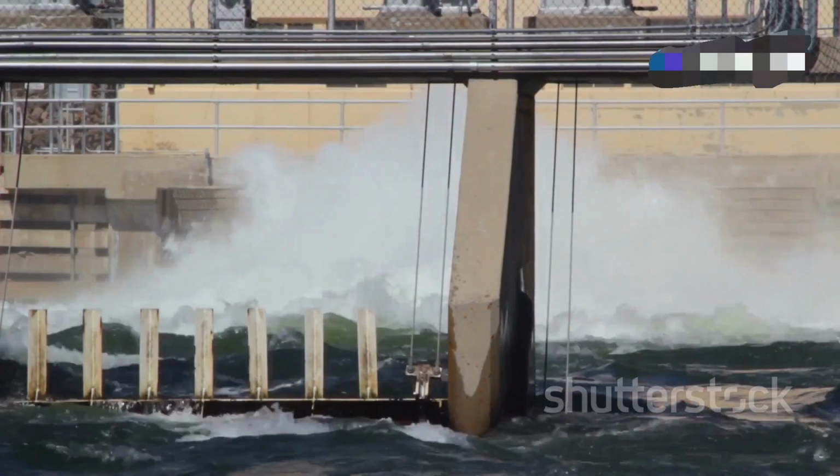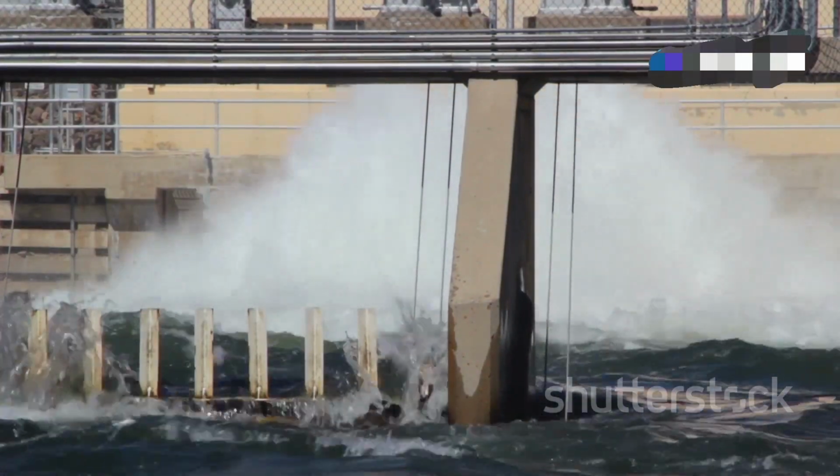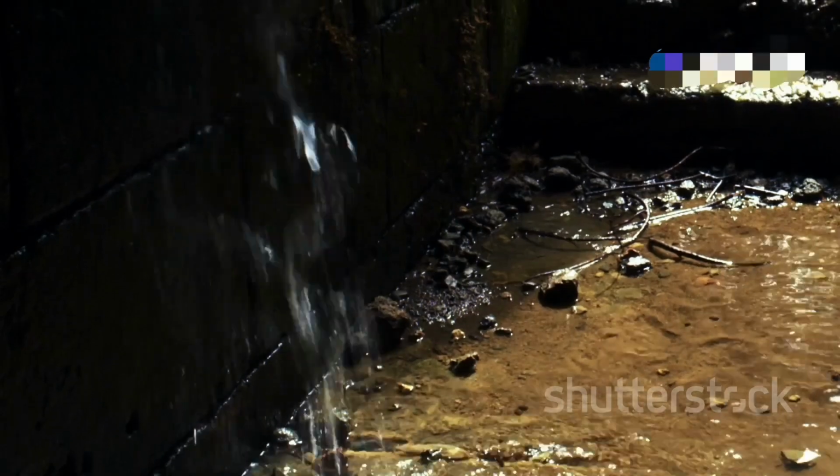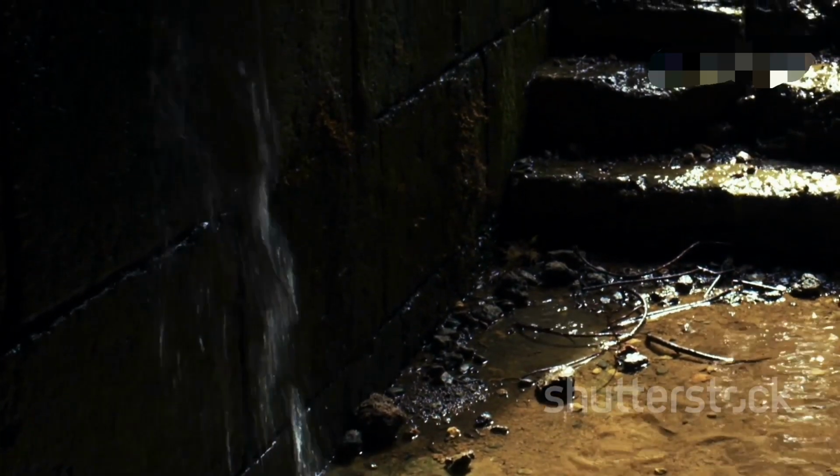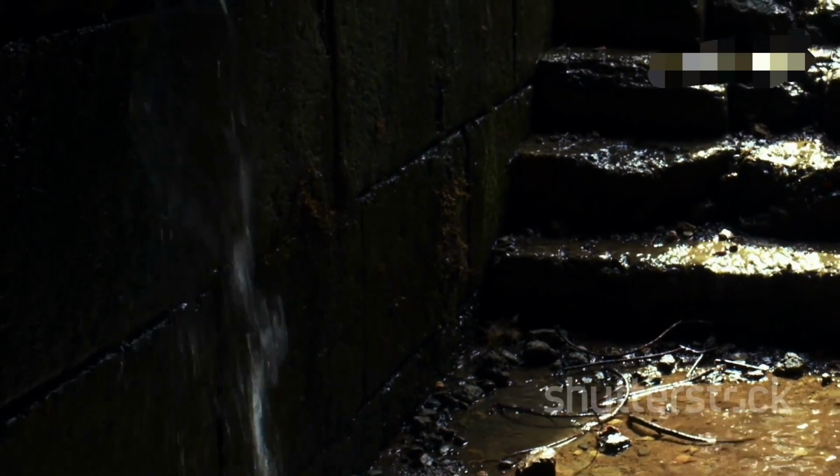Overtopping occurs when the water level in the reservoir rises above the crest of the dam. Piping is when water seeps through the dam, creating a small tunnel that gradually enlarges. For concrete dams, failures might involve structural issues like cracking, sliding, or overturning of a monolith section, often related to foundation weaknesses or extreme loads.